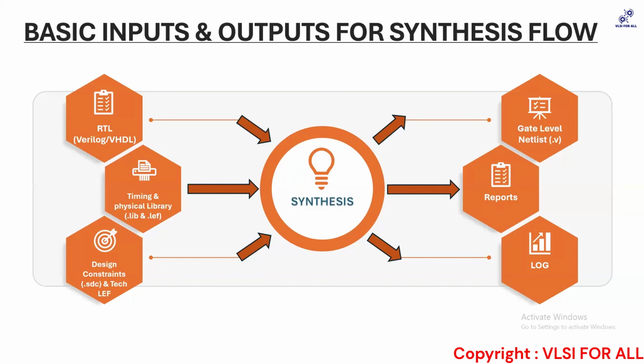For example, while doing the synthesis, they have generated some logic. It can happen that PNR folks can alter it during their optimization, but you want this logic to remain untouched. I don't want it changed, even if they're trying to optimize. You can put don't touch on it. So these are additional constraints along with your normal constraints, and you have to provide them to your PNR folks.